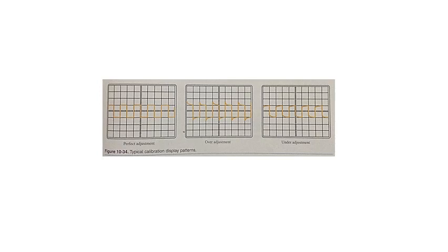The oscilloscopes can also be connected directly to a personal computer. This is referred to as data acquisition or transfer. This application usually requires an expansion card for the computer, software to run the program, and an interface cable to connect the oscilloscope to the computer. These peripherals are often provided with the scope. A personal computer used in this way will display the wave patterns, voltage, and frequency of the wave form. The information can be downloaded directly into documents for use in reports or training manuals.